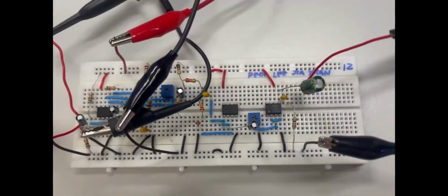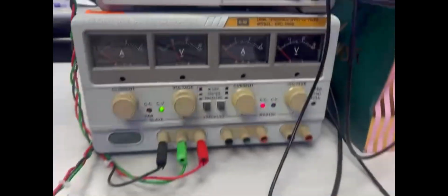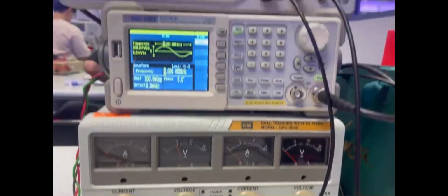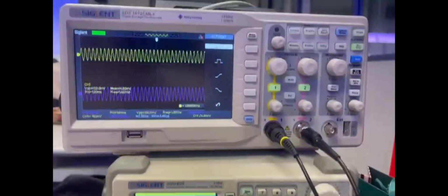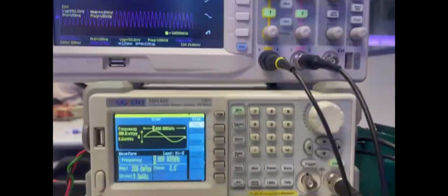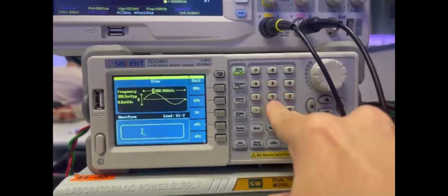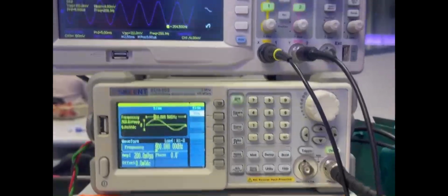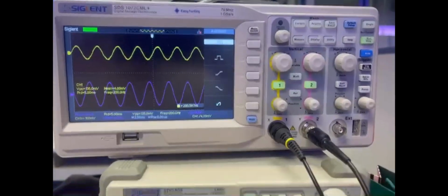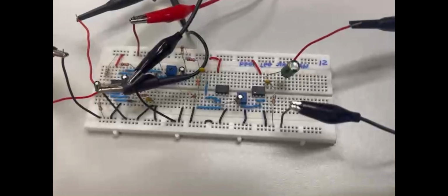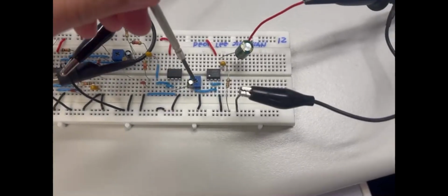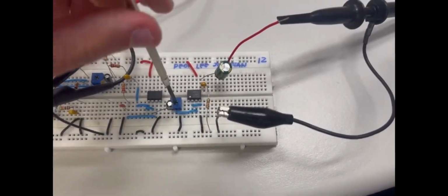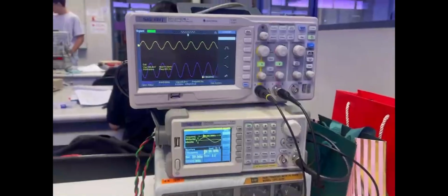At TP5, 200 Hz, 200 mV peak to peak, my voltage output is 5 V. But when I set the frequency to 1 kHz, at 200 mV peak to peak, my voltage output is 3.20 volts. And in the video, I have adjusted the trimmer to show how it amplifies the waveform. Once the waveform is amplified to saturation, the waveform is cut out.